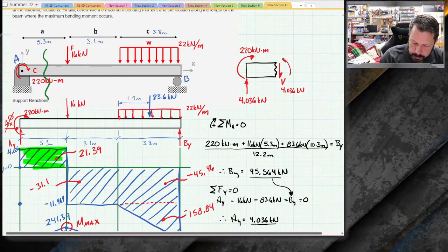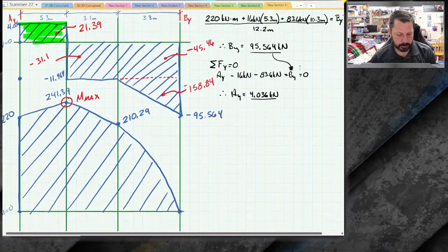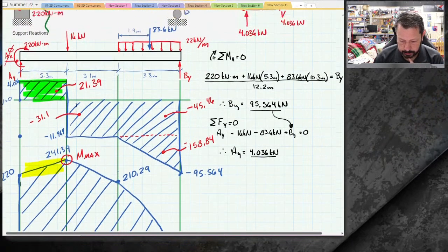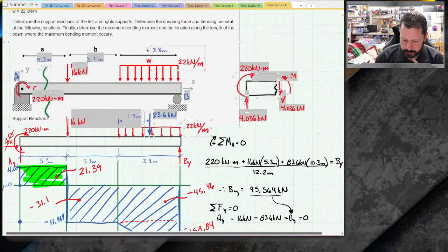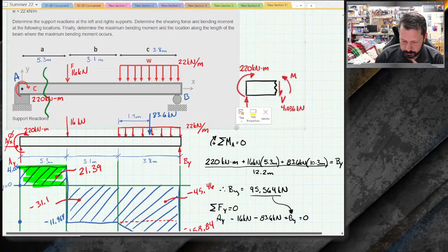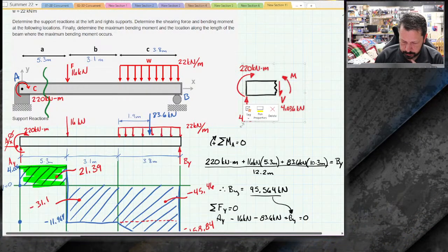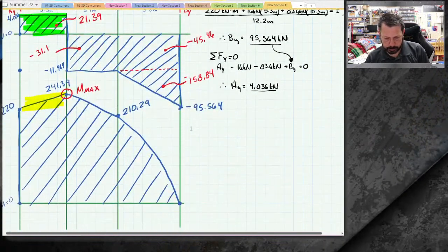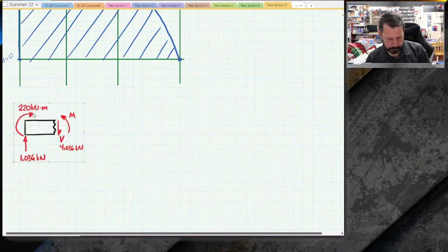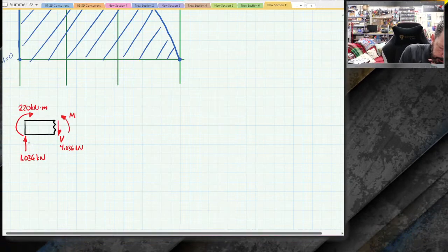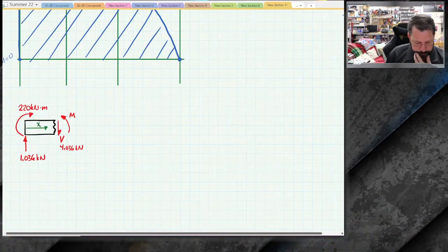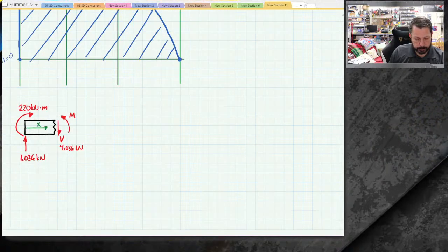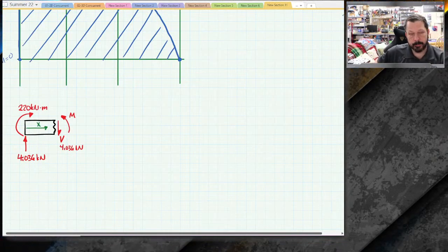And then there's that internal bending moment. This bending moment is this thing. The equation of that line will be what we solve for when we write the equation we're about to write. Let me put this down here just so we can write around it. And also we have our x-axis. All right, so we don't really need to write the summation of forces in y to get the fact that V equals 4.036, but that would be how we would calculate that one.